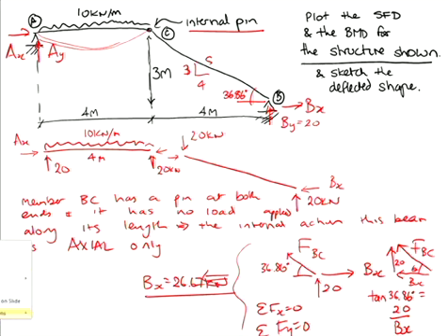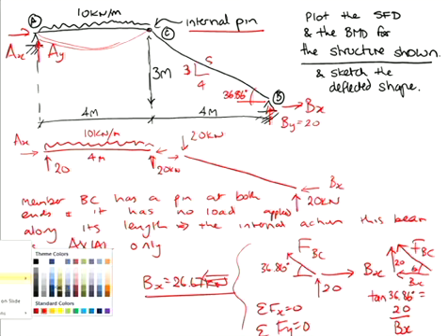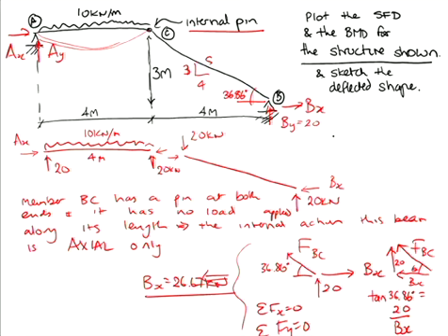The other way you could look at it, as an alternative now, I'll go back to another pen colour that's easier to read. Okay, I can base on these free body diagrams. Why don't I take moments at C? And taking moments at C, we know that the sum of the moments has to equal 0 because it's in equilibrium.